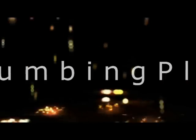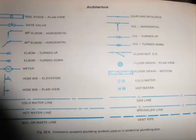The plumbing plan. And now, to help you better understand the plumbing plan, we have here the different symbols used in the plan. Let's start with the first column. The first one is what we call the soil stack plan view. Next is the gate valve, then the 90 degrees elbow horizontal, the 45 degrees elbow horizontal, the elbow turned up, and the elbow turned down. Then we have the meter, the hose bib elevation, and the hose bib plan view.